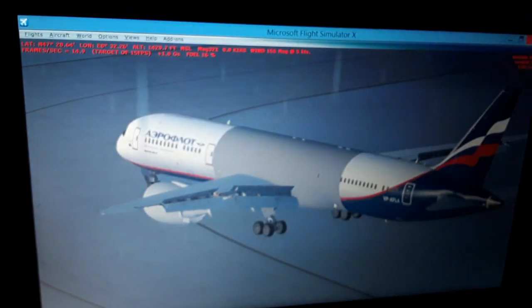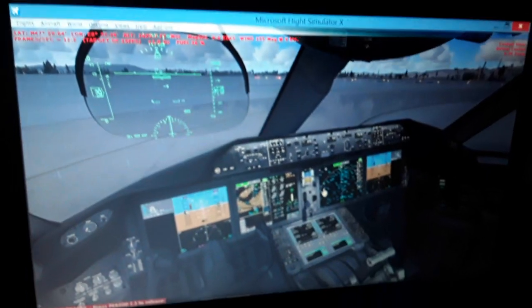We have also the navigation display. You can see the navigation display that displays the GPS position of the aircraft, the inertial reference position, the magnetic heading and track, the magnetic north pole and true north pole, and the magnetic variation depending on where we are in the world. You can see the horizontal and vertical profile of the terrain displayed with red, green, and yellow colors. Also, you can see other indications like how far above the terrain the aircraft is flying or how far away.